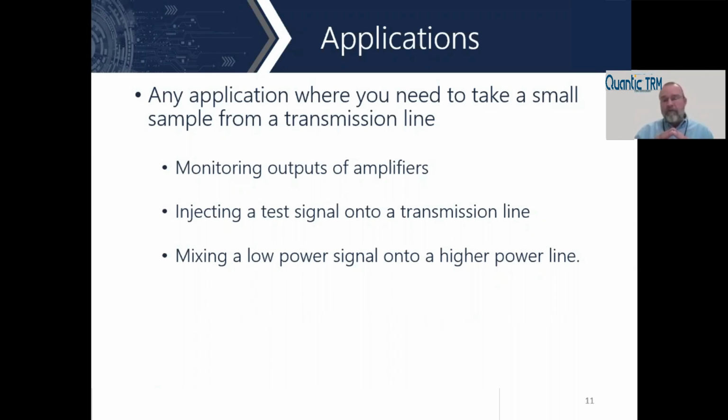It is not uncommon, for example, for a high power amplifier to have a 40 dB coupler going forward, making sure we have a reasonable amount of power coupled back from the transmitter. But because the reflected energy is so much lower, maybe you want to have a 20 dB coupler, for example, on the reflected side of that dual directional coupler.